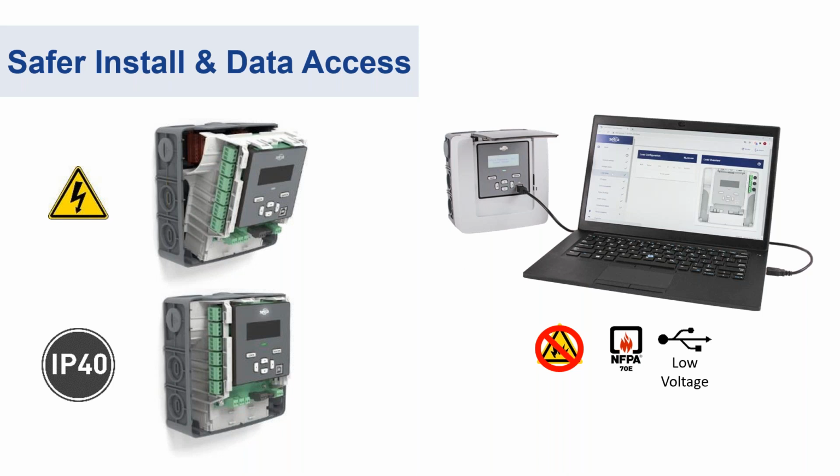You can also set up the meter to be accessible via RJ45. So if I had the cover off of this, actually, let's look on the bottom left-hand side of the screen. Underneath the display, there's actually an Ethernet cable. So that cable style is called RJ45. So another method of connecting a computer to this might be just using a standard Ethernet cable that you use with any home router. Again, nothing proprietary about it. There's just an ability to have either one of those cables used for the configuration.